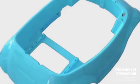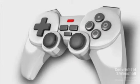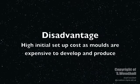Injection moulding is used for making casings for toys, plastic components, casings for electronic products, as well as games controllers. The advantage of this method is that it's ideal for mass production as it has a low unit cost when mass produced. It is also highly accurate and gives a high quality surface finish. Also, textures can be added to the surface easily. The disadvantage, as with blow moulding, is that there's a high initial setup cost as moulds are expensive to develop and produce.